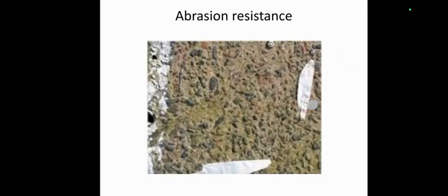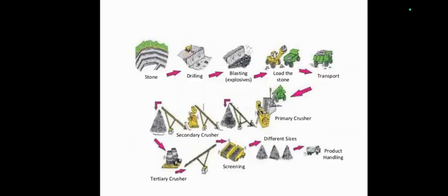Regarding the extraction of aggregate, as you already know, the main source of aggregate is mountain rocks. So they will construct a quarry near a mountain, and by using some explosives they will break the rocks into small pieces, load them in trucks, and send them to the quarry where sieving and screening will be done, and then it is crushed by a jaw crusher.